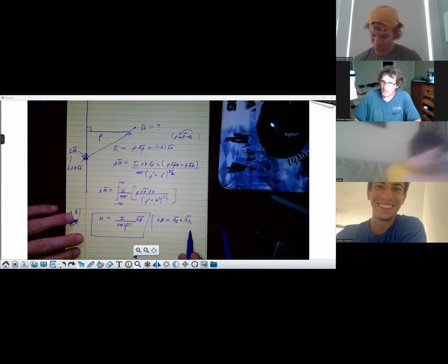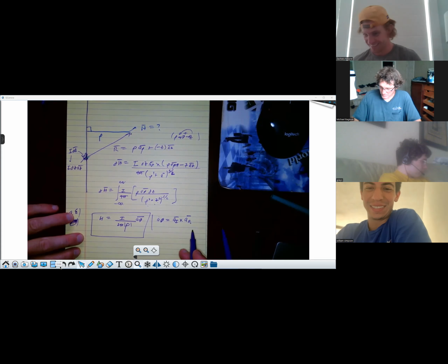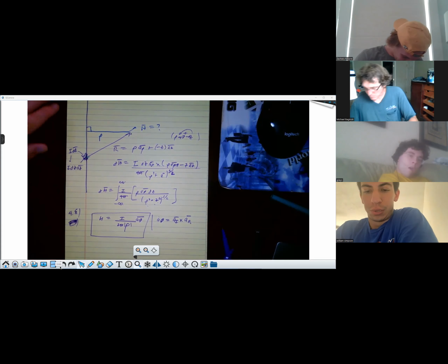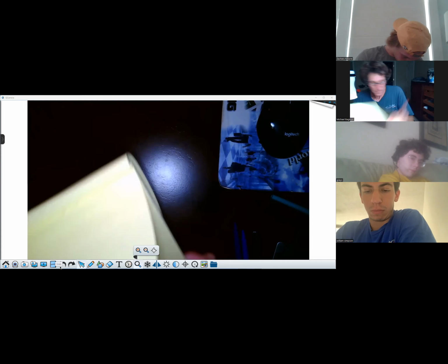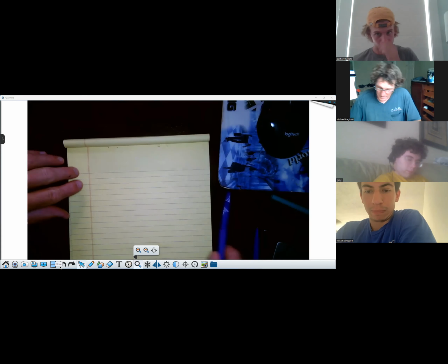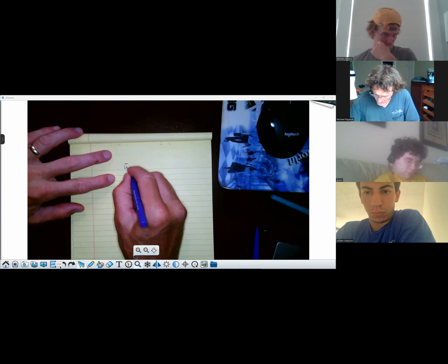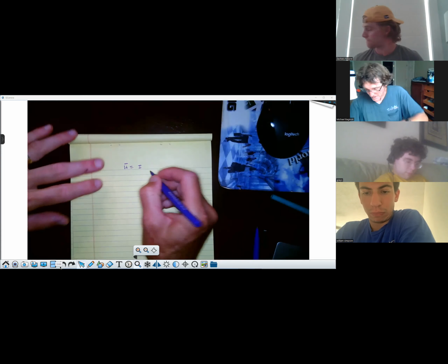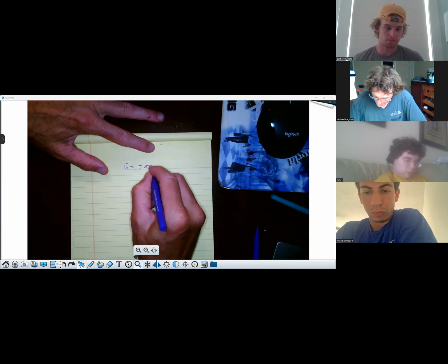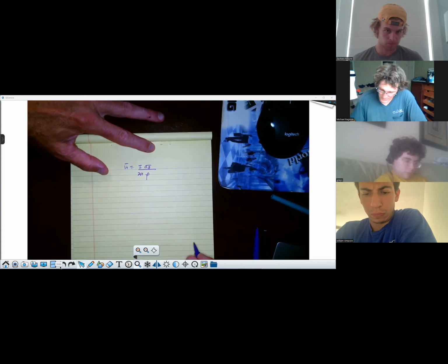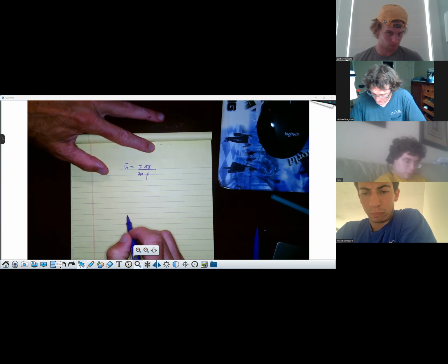Anyway, if you take a look at this right here, this makes perfect sense that the current's on the z-axis. But what if it's not on the z-axis and you still have an infinite current? Now I want you to pay attention. Suppose it's an infinite current, the H field is equal to I over 2 pi rho, A phi. Here, rho is the magnitude from the axis of the infinite current to the point of observation.